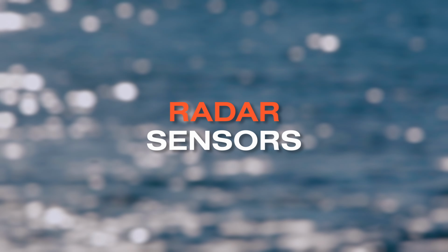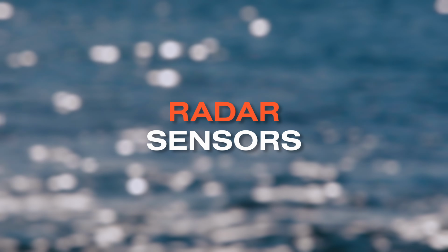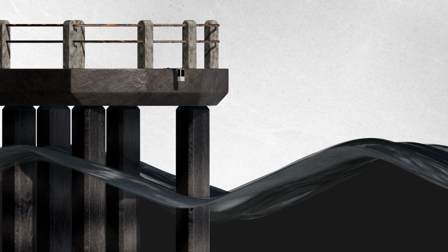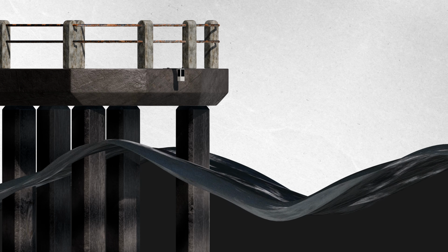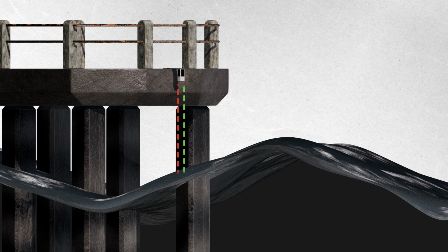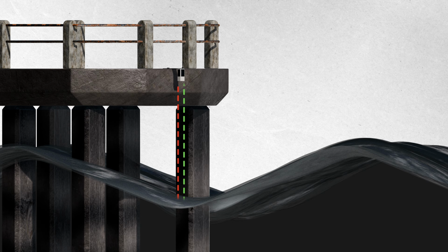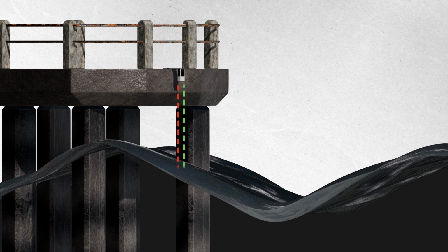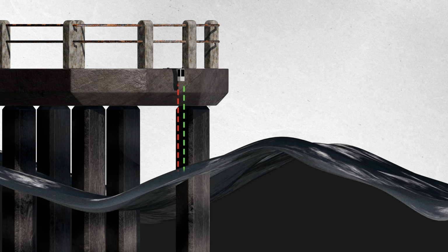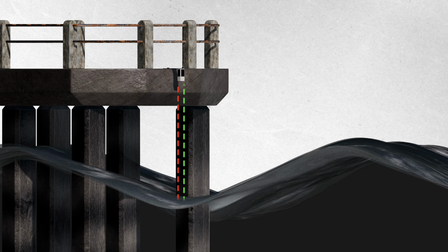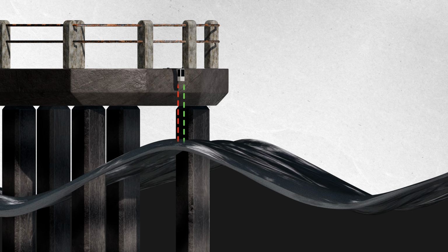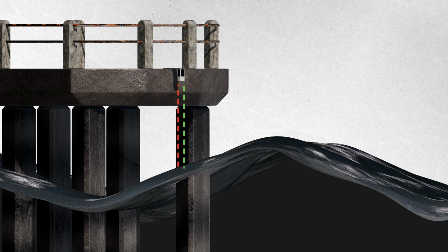The third major technique uses radar technology. A radar sensor is mounted above the water surface on a platform, a bridge, or any elevated structure, and it points downward at the water. The sensor sends out radar pulses and measures how long they take to bounce back. Since we know the speed of the radar signal, we can calculate the distance to the water surface with remarkable precision. As waves pass beneath the sensor, the distance changes continuously, and by recording these distance measurements over time, we get a surface elevation time series, just like with the other methods.